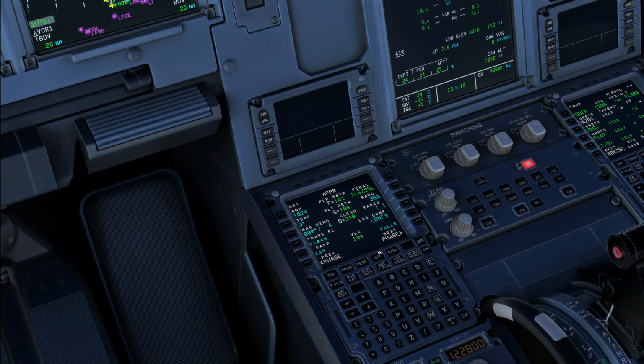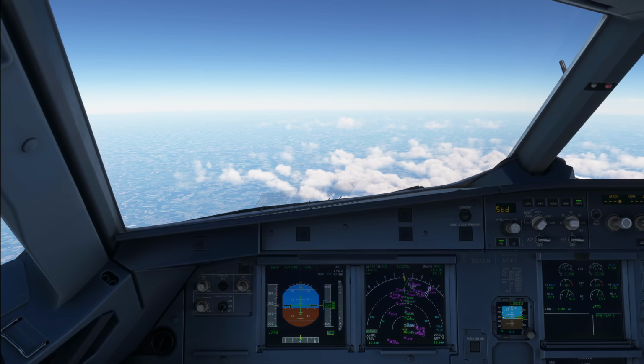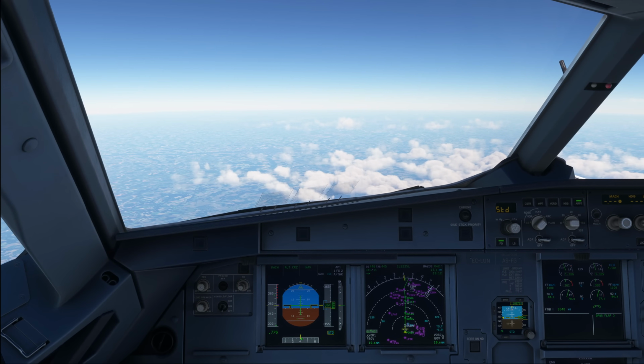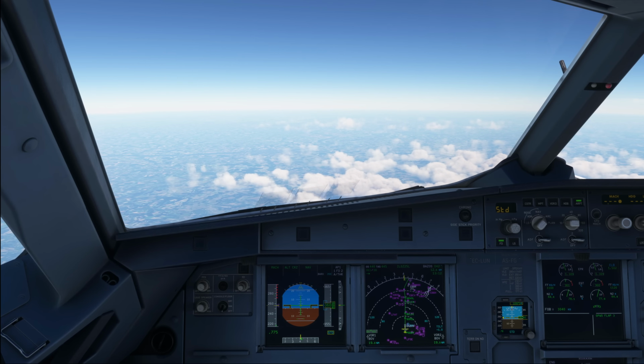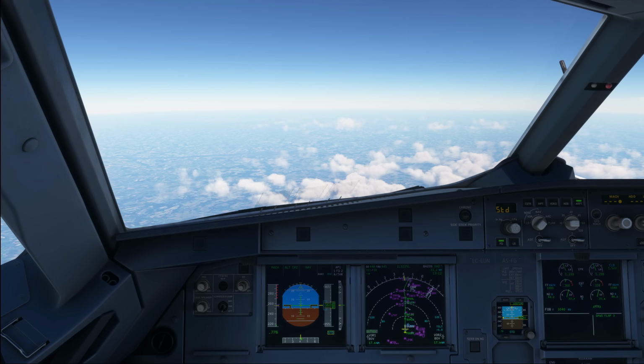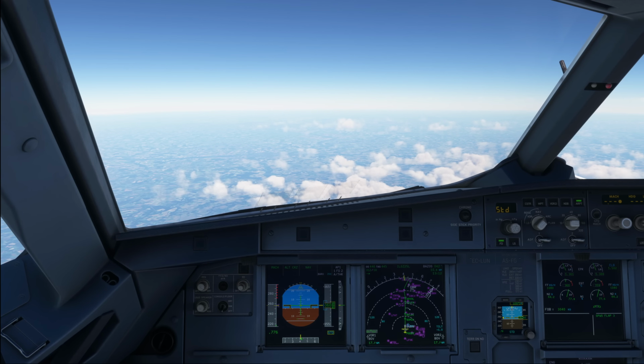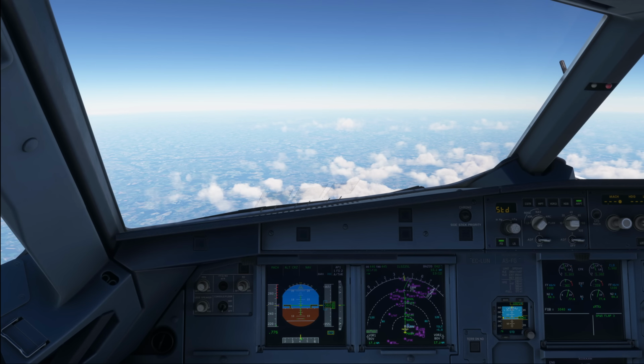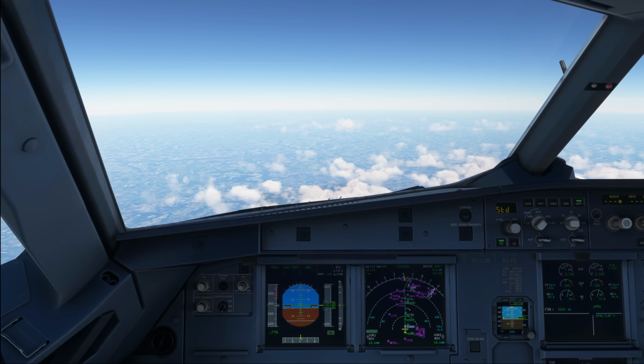However, always take additional factors into consideration, as I have explained in my video on how to choose your landing flap setting. So going ahead then, in the actual descent, it is recommended to fly managed speed and fly at the econ speed, which optimizes speed in accordance with the cost index and flight condition of the day. When you have to conduct a holding on the approach, clean configuration is recommended. However, config 1 may be used if you've got holding pattern or speed limitations. Optimum speed in clean configuration is green dot speed in order to optimize the lift to drag ratio.